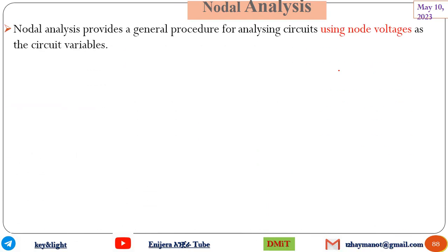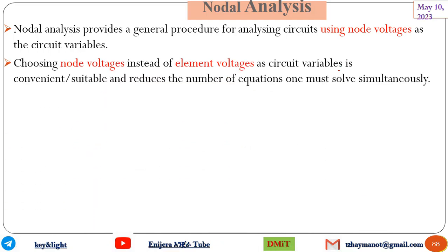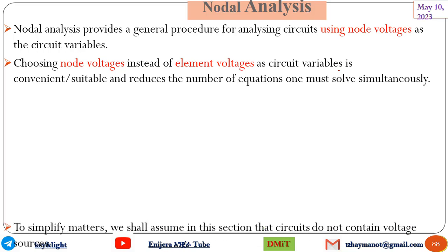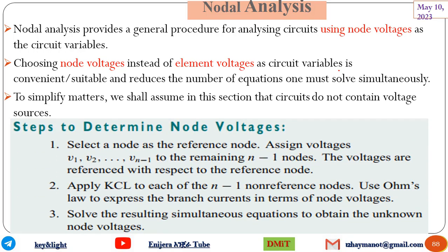The other is nodal analysis. Nodal analysis provides a general procedure for analyzing circuits using node voltage as a circuit variable. Choosing node voltage instead of element voltage as a circuit variable is convenient, suitable, and reduces the number of equations one must solve simultaneously. So, we have to remember these steps.